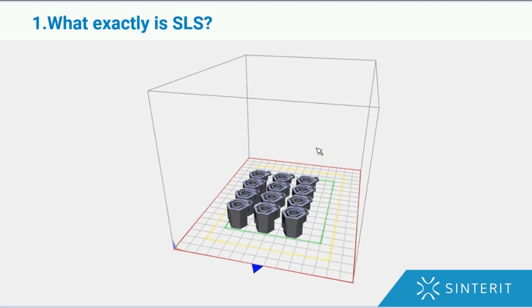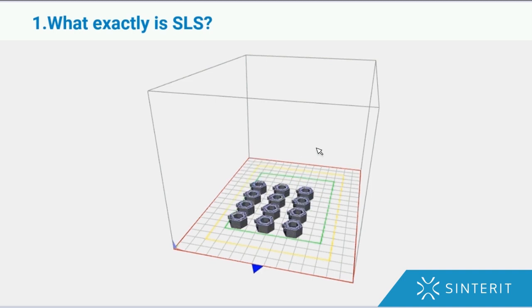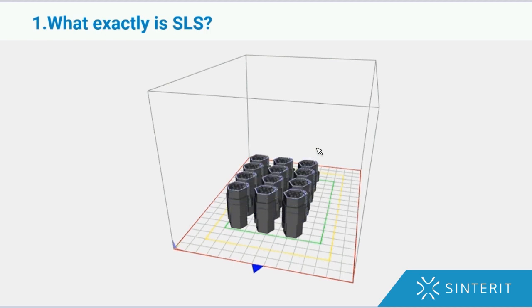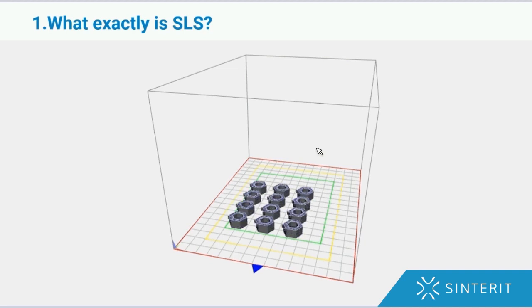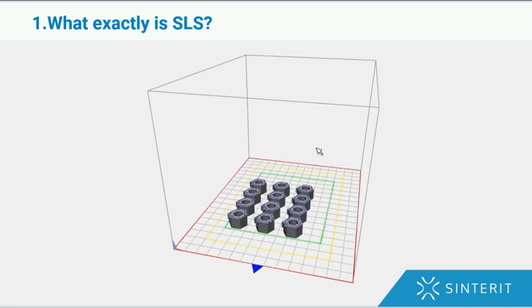And the SLA acronym describes stereolithography. It employs photopolymerization using light to link chains of molecules together and form a polymer 3D structure. All of those methods can be seen as forms of microscale clay modeling or clay making processes, but they are using different methods to glue the structure together, and so they are all additive manufacturing processes.